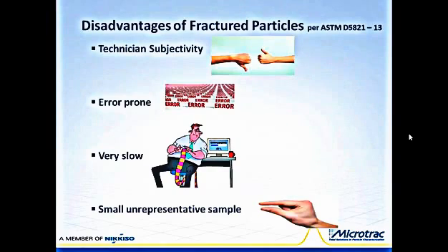Disadvantages of fractured particles: technician subjectivity. This is a very subjective test with a high chance of different technicians coming to wide differences in results. Error-prone in visual judgment, counting, recording, and calculating results. And it's a very slow process. It's run on, again, a very small, unrepresentative sample.